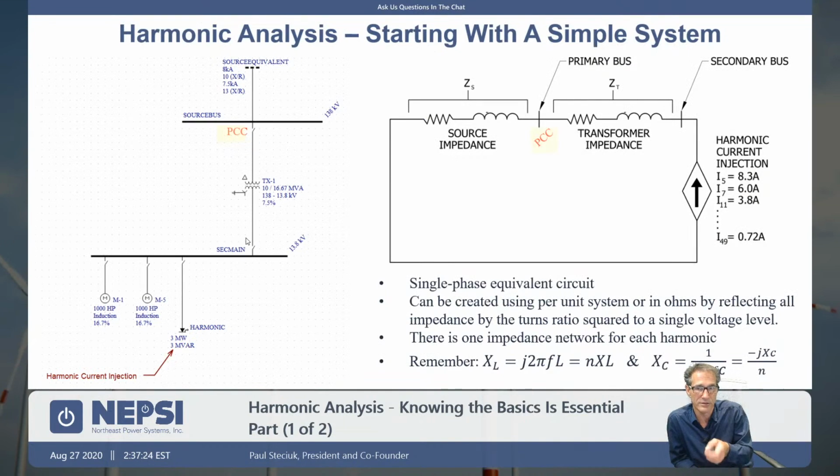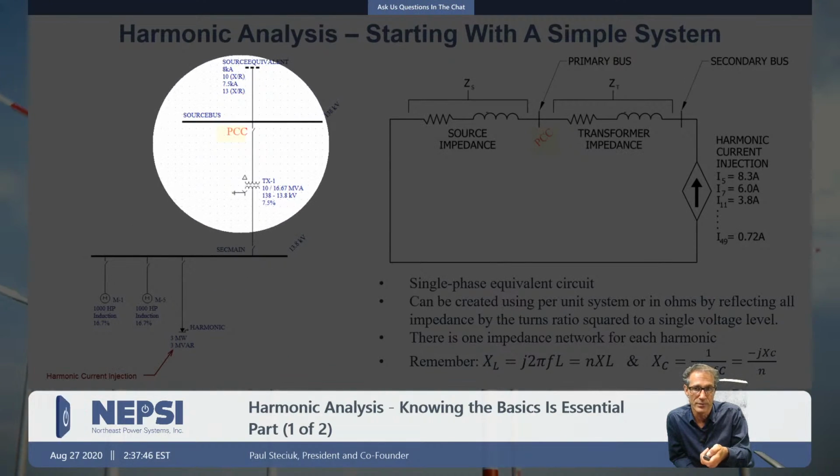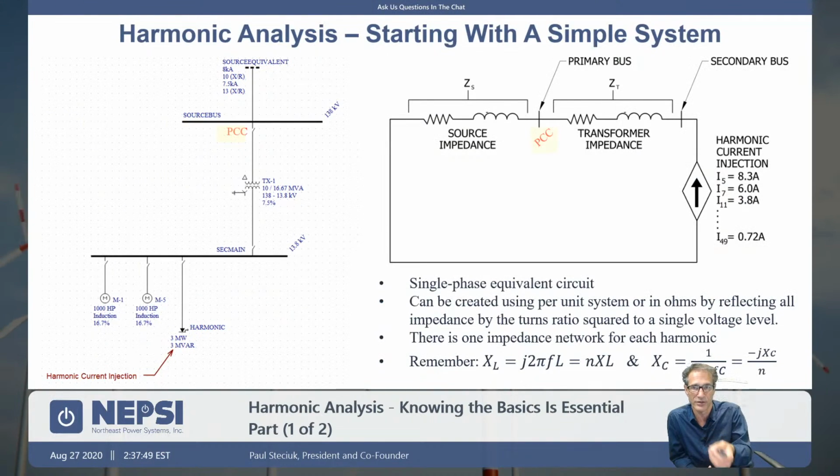Now, IEEE 519 doesn't dictate that value, but if you're designing for a relatively good standard of power quality, the desire is 5%. So for me, when I do harmonic analysis to come up with a filter design, or if I'm adding capacitors to a network and I want to determine what my limit is, I use 5%. I also look at the current at the point of common coupling. If the utility is monitoring for IEEE 519, you want to be within those IEEE standards. So that's the two key values I'm looking at: current distortion at the PCC and voltage distortion within the plant itself.